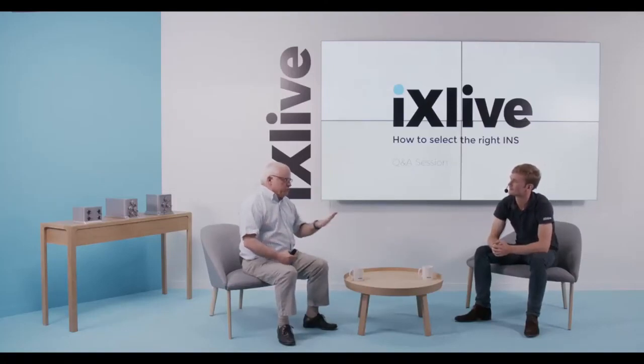Okay. And you need very high performance sensors for that. Okay. But most of the time, it's not possible to do it. So you have to know the position from another means. The most popular and the easiest one is the GNSS. Yeah. But if GNSS is jammed, you have to know the initial position by knowing where you are on a map. And so you can input this data in the INS as a starting point.